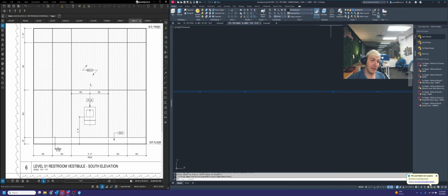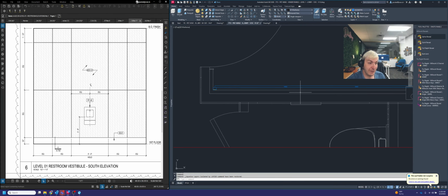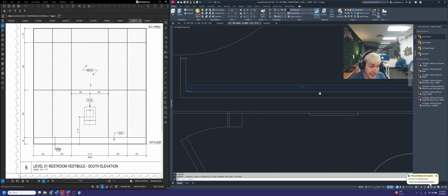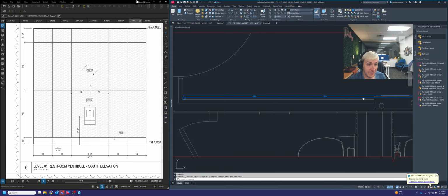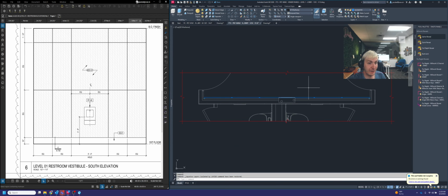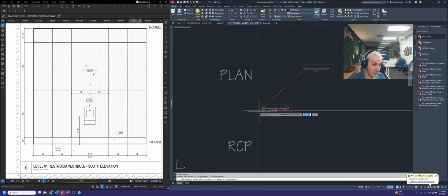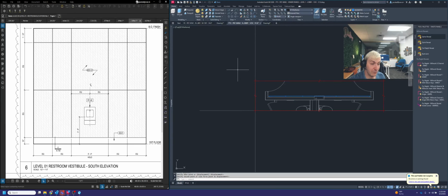I'm going to bring back all my layers by clicking on isolate, or the stack of papers with the upward facing arrow right there under my layers. Okay, and that'll do it for the plan view. We're going to come back and hatch these in a little bit, so that way you're actually seeing hatching through these panels, because we're kind of treating it like a horizontal section view through the panels. So we'll take care of that here in just a moment. For now, since we're about done with that, what we're going to do is use the move command, move that plan view to the corner of my view grid right here.